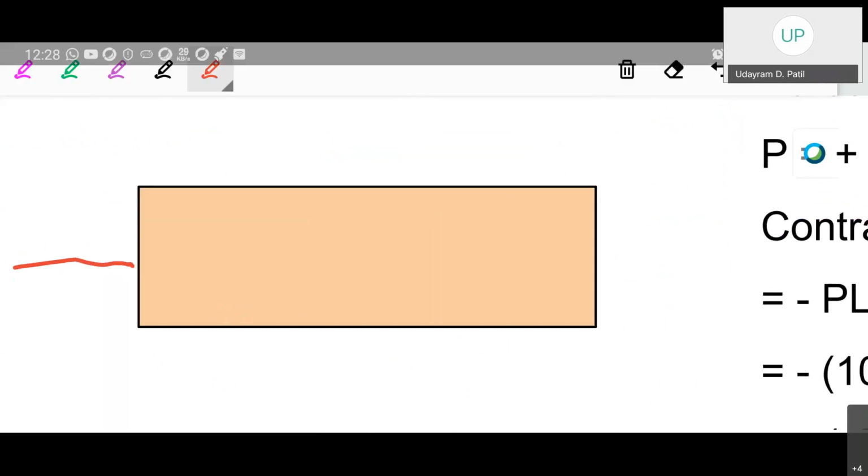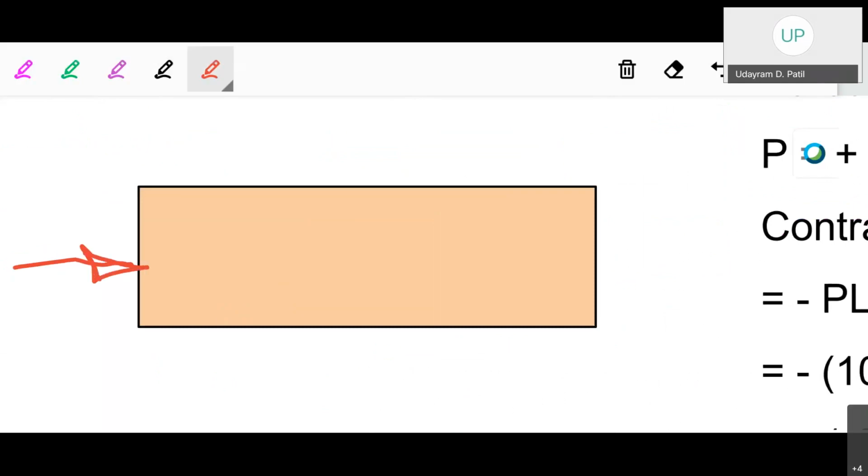Okay, so applying the same force on this particular section, and here again applying the opposite. Whatever the section is, if here the particular section loading is like this, then we are going to consider the opposite at this particular section. Here the loading is towards the right, therefore again considering the opposite, that is towards the left. As you can see, both of the loads will be of the compression type, therefore the change in length will be negative, or the particular member will be compressed.